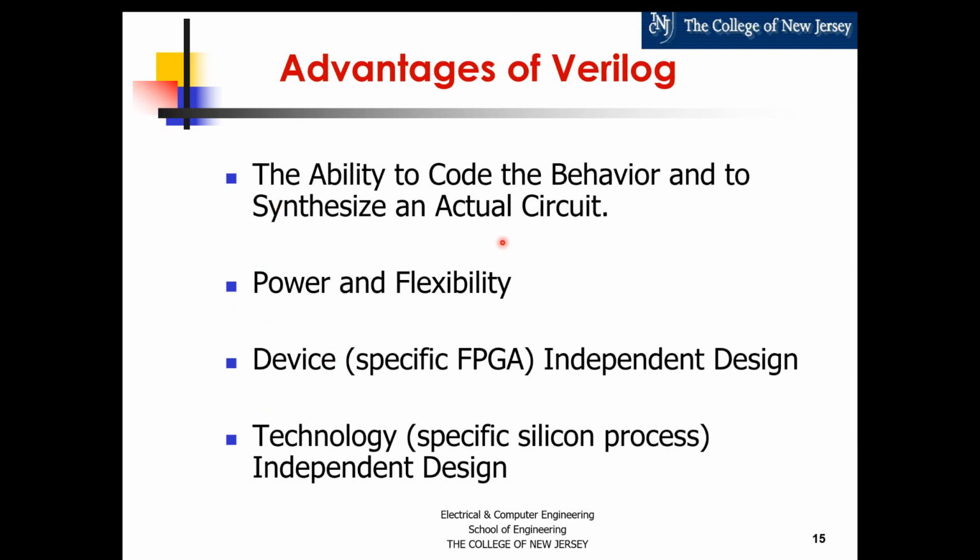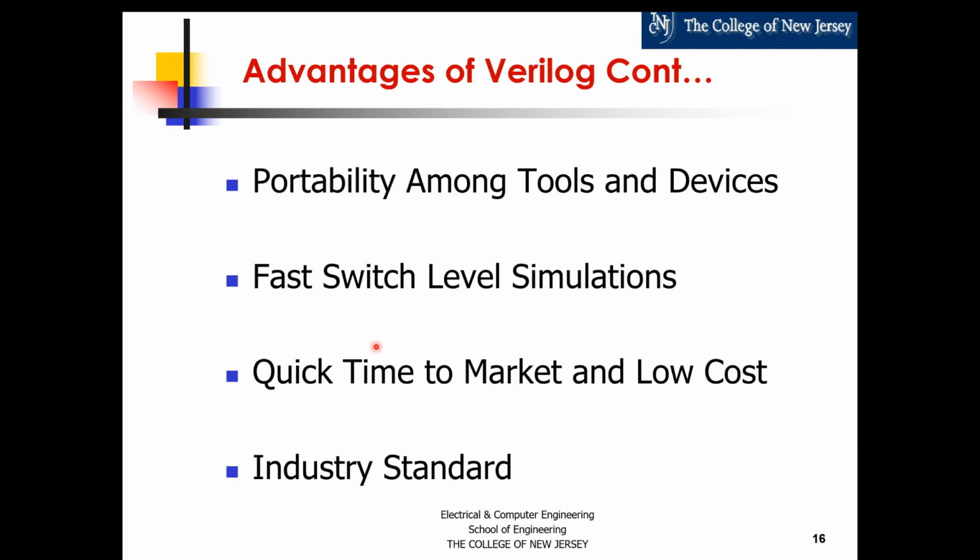So I already talked about the ability to synthesize and the flexibility and the portability. So let's keep going. Now, another thing that I wanted to mention is that this type of logic simulation, where you are really abstracting the transistors, as opposed to something like a SPICE. Imagine if you had to do billions of transistors or gate type chips with things like SPICE, it would take forever.